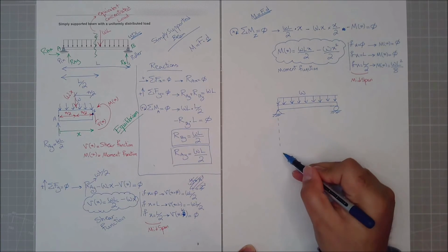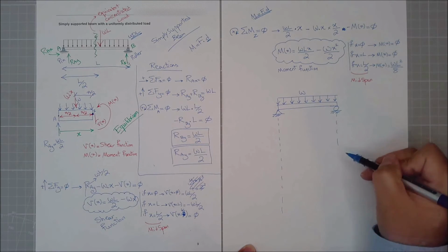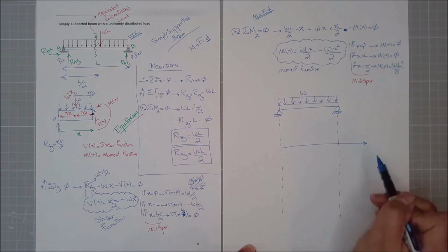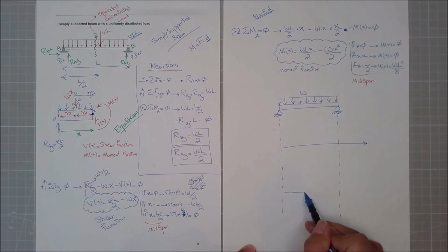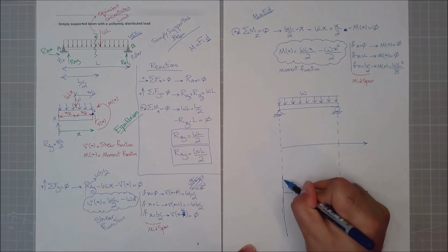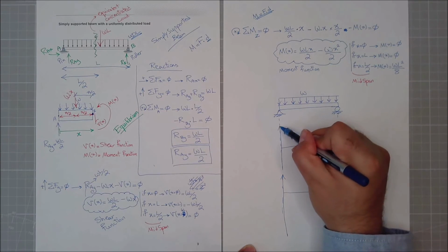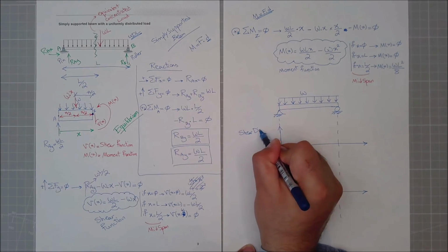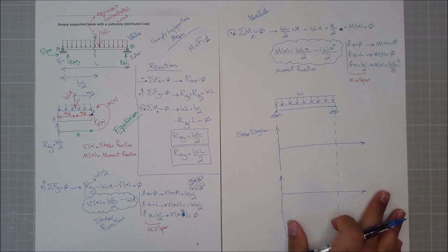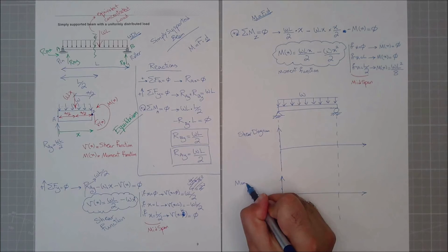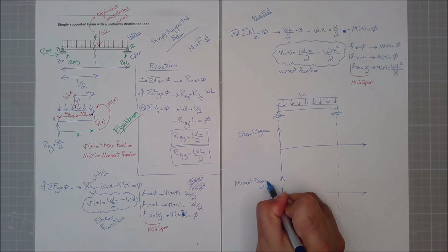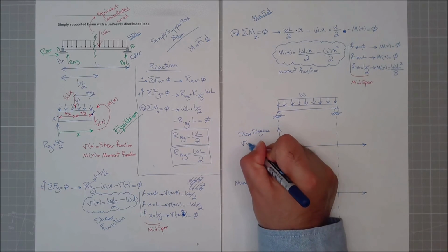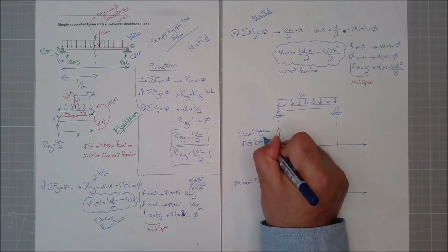As I mentioned, we do some dashed lines to follow exactly the length of that beam. Let's say one of them will be for the shear and one of them will be for the moment. So this for the moment and this for the shear. This will be the shear diagram. This will be, oopsie, the moment diagram. If its shear is V of x, the unit, for example, is in kilonewtons or newtons.